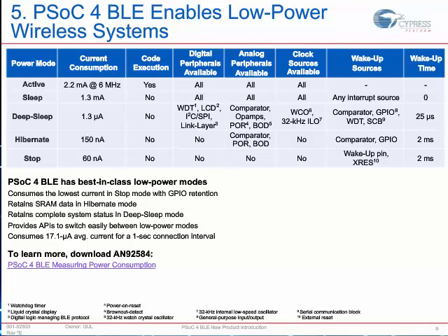So when I need the information from that sensor, it's available to me on demand. It's already sitting there in a well-conditioned state for my ADC to pick up, convert into a digital value, and send to my host cell phone over a BLE wireless link. So that's a very, very useful mode, and the wireless link here is enabled by a watch crystal oscillator, which is a 32 kilohertz crystal.